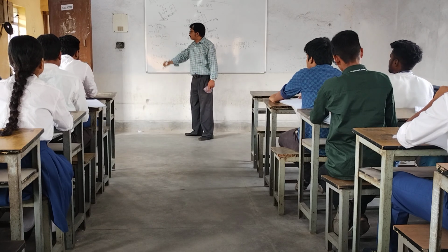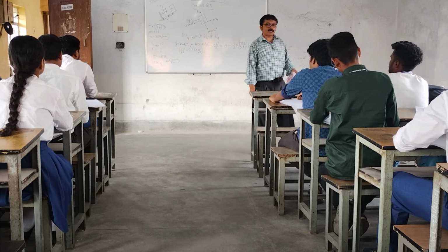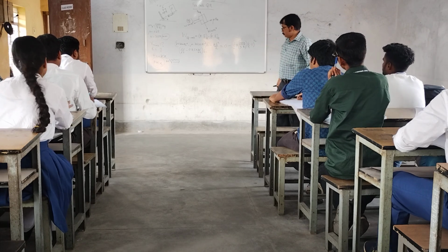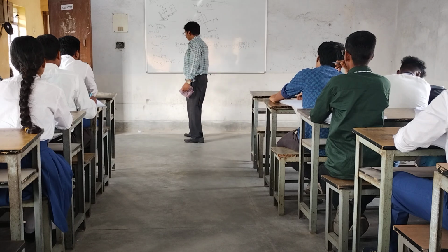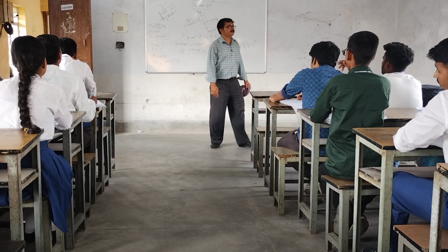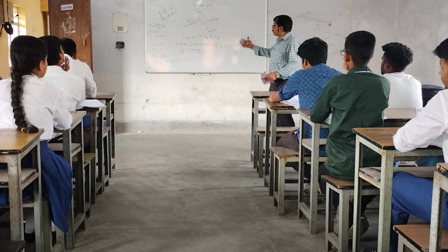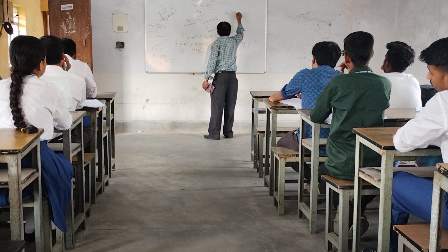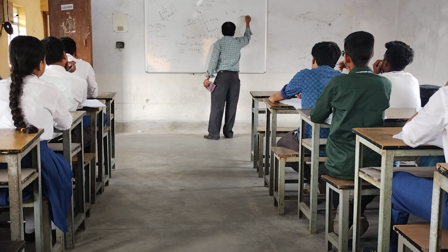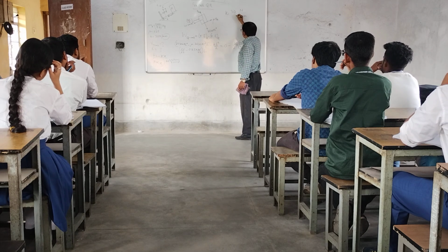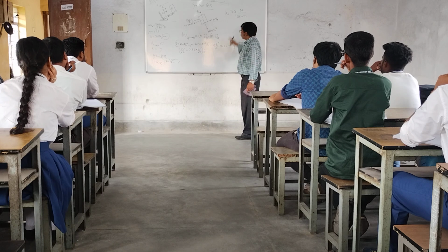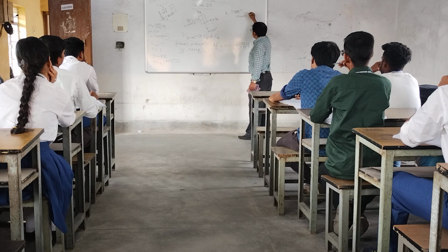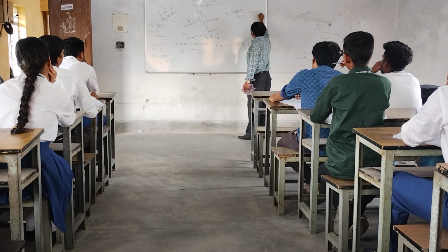You have to be very careful. The stiffness 30 newton per millimeter remains; you should write the value as newton per meter because we are using SI units. Converting the denominator from millimeter to meter, multiply the denominator by 1000 and the numerator also by 1000, so it becomes 30,000 newton per meter.